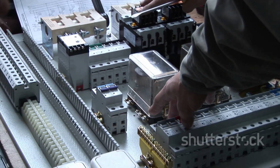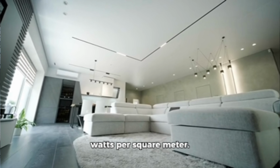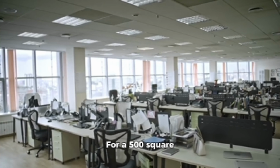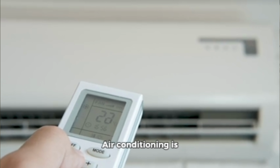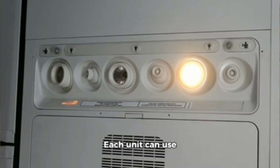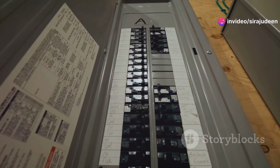Lighting is another big one. Modern LED lights are efficient, using about 10 watts per square meter. For a 500 square meter office, that's 5,000 watts. Air conditioning is crucial for comfort. Each unit can use 2,000 watts. For 6 units, that's 12,000 watts.